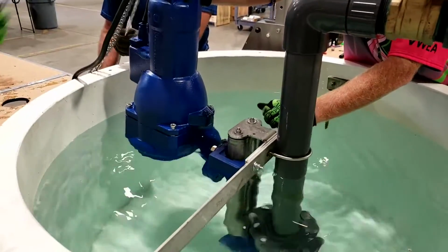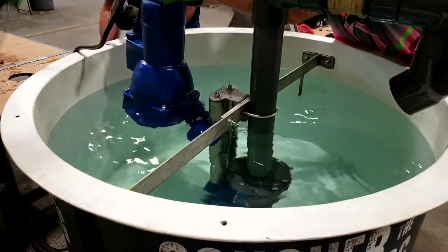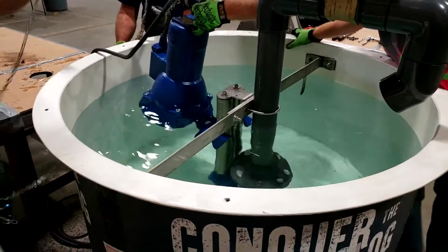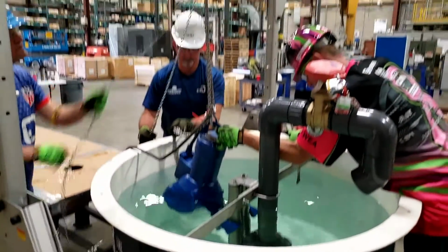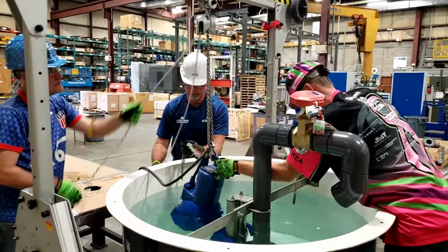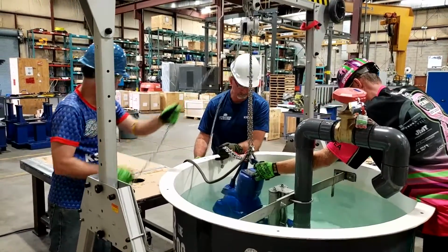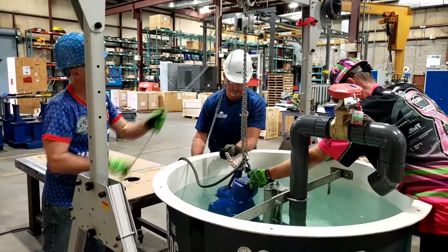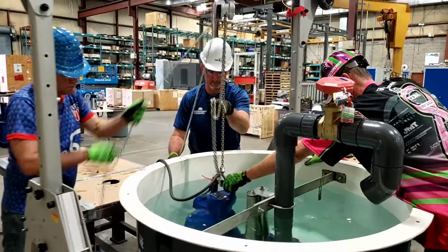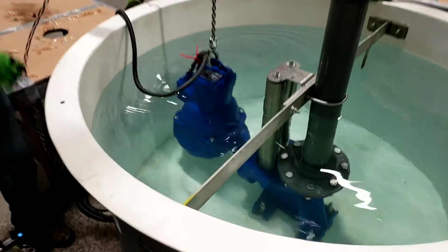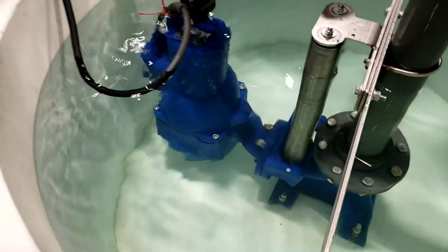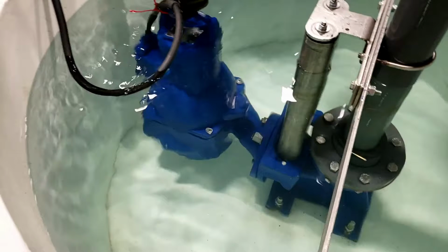You will need to guide the pump onto the guide rails. Ensure you are lowering the pump in such a manner and angle that the volute, seal, or gasket is seated properly in the elbow and not pulled out. To ensure you have the best chance at a good seal, the hook should be placed on the pump handle as far away from the guide claw as possible.